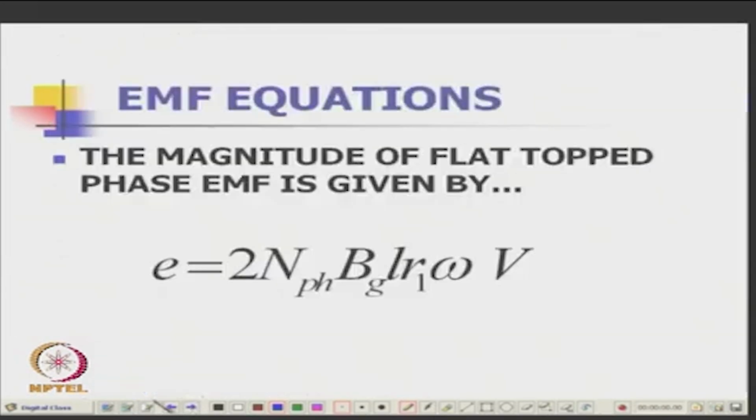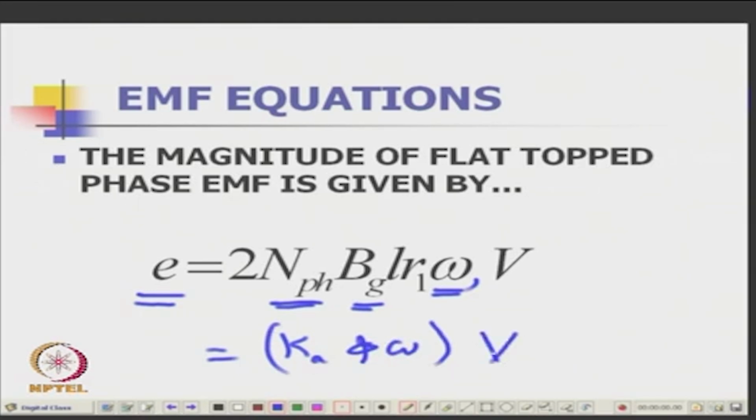So, that is why we said that while this will be the voltage induced, which is proportional to the flux density, number of turns per phase, and the speed omega, so many volts, right. That is the, so it will be some constant into flux per pole into omega, okay, so much of volt, that will be the induced voltage in this.